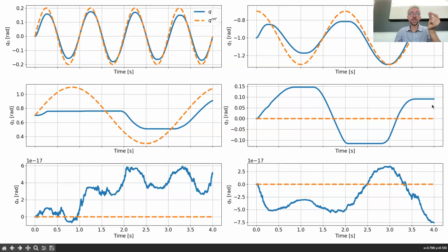And this is an effect, again, of Coulomb friction, which is counterintuitive in a certain sense, because Coulomb friction should only make the joint move less, not move more. So why is this happening? Yeah, the phenomenon is clearly stick slip. Here we have a sticking phase and then it's slipping, sticking, slipping.